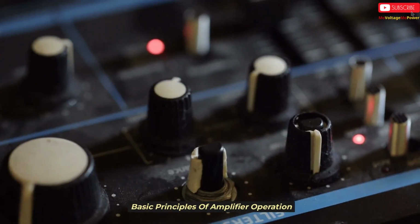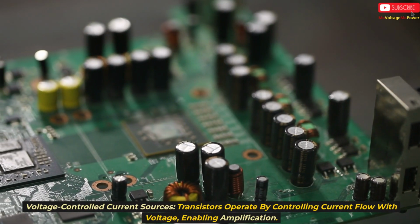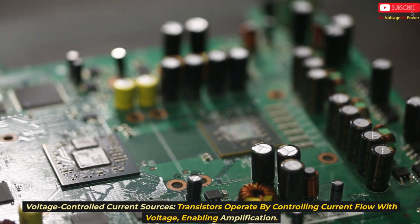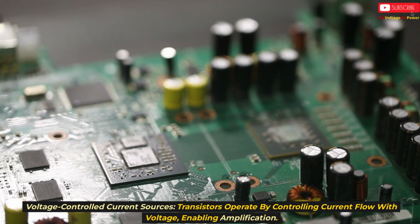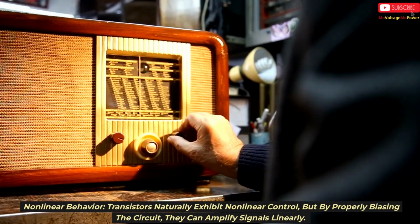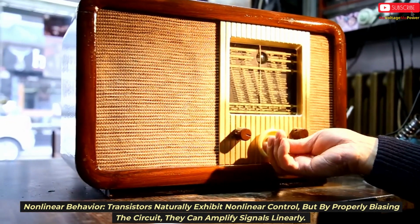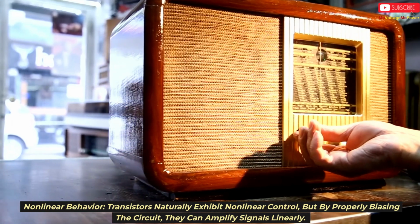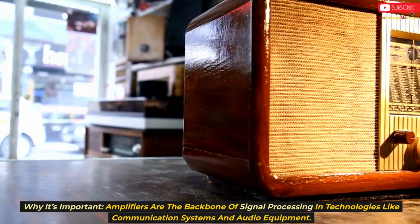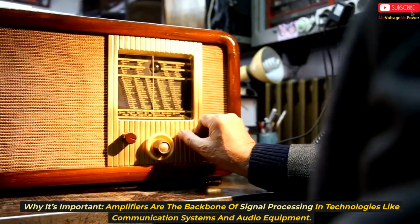Basic principles of amplifier operation. Voltage-controlled current sources. Transistors operate by controlling current flow with voltage, enabling amplification. Nonlinear behavior. Transistors naturally exhibit nonlinear control, but by properly biasing the circuit, they can amplify signals linearly. Why it's important. Amplifiers are the backbone of signal processing in technologies like communication systems and audio equipment.